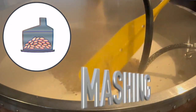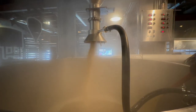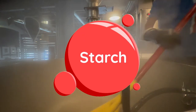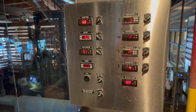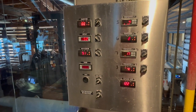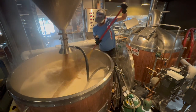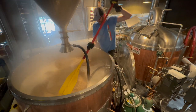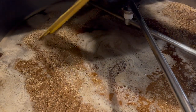Step 3. Mashing. The milled grain is transferred to the mash tun, where it's combined with hot water in a process called mashing. During mashing, enzymes from the malt convert starches into fermentable sugars. The temperature of the mash affects the character of the beer. Lower temperatures produce a more fermentable wort, leading to a lighter-bodied, drier beer, while higher temperatures leave more unfermentable sugars, resulting in a fuller-bodied, sweeter beer. After about an hour, we're left with a sweet, porridge-like mixture called the mash.